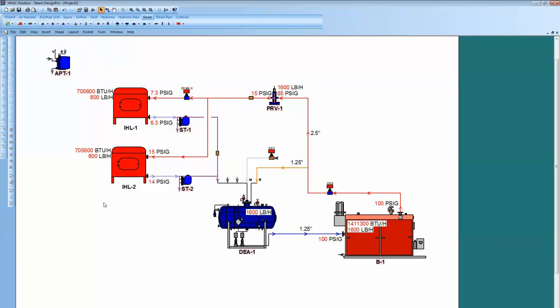Okay. So there we created a simple steam system with the 4 major system components: generation, distribution system of piping, imposed loads, utilization of some type, process there, in this case autoclaves, and then the condensate recovery with miscellaneous smaller minor steam parts, meaning the traps, control valves, PRVs, whatnot.